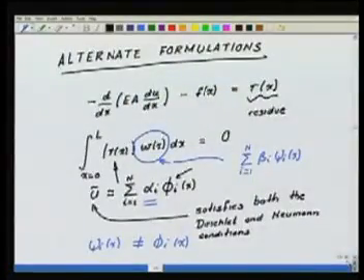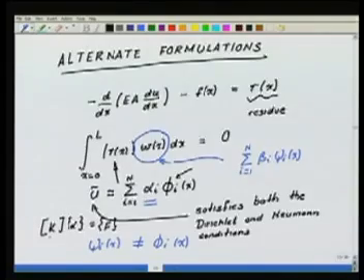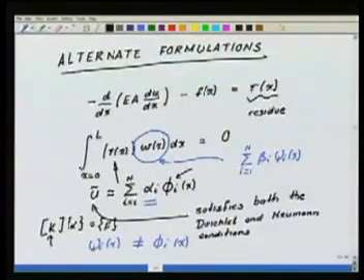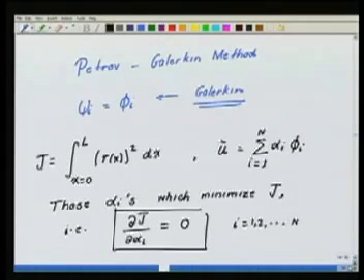If I go back and look at the Petrov-Galerkin, here for I and j, if I replace I with j, I need not get the same entry. See, here also I will have some k into alpha is equal to f, but the kij need not necessarily be equal to kji. So this matrix is going to be unsymmetric, and that comes with its own set of problems.